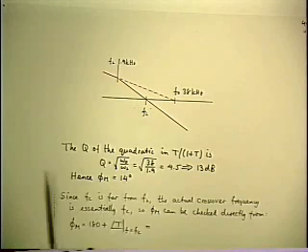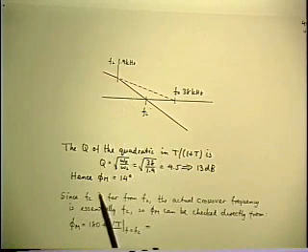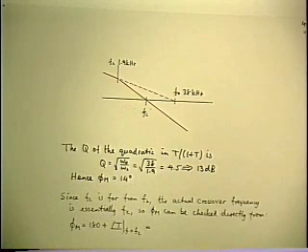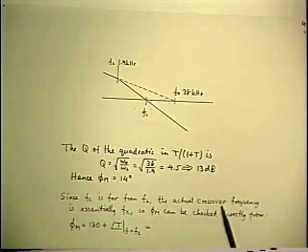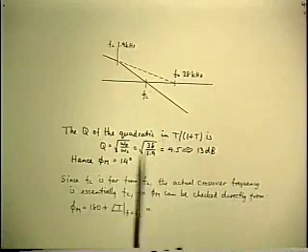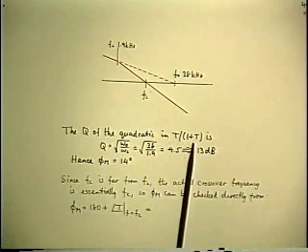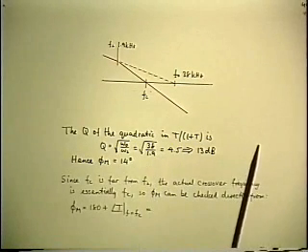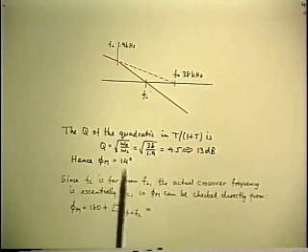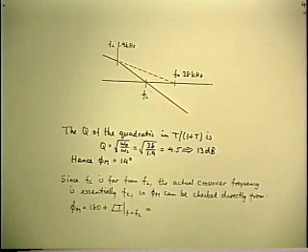Now, of course, if you've done your design and you put the numbers into this point and you get this sort of answer, there wouldn't be any point in going into the lab and building it, because this obviously would be unacceptable. But for the purposes of illustration, let's go ahead and do that. So, if I build it on the bench, at least it's going to be stable because the phase margin is positive, even if it isn't small enough.